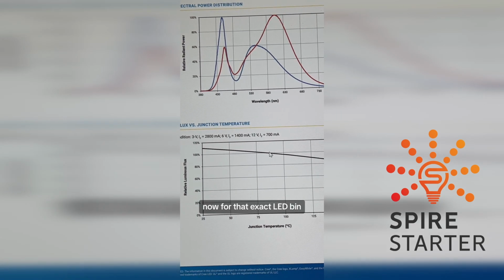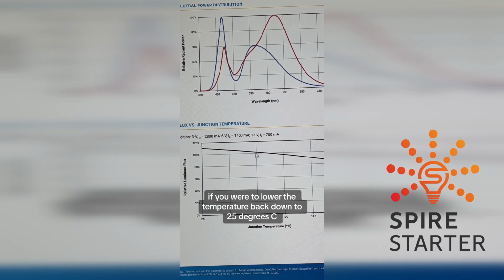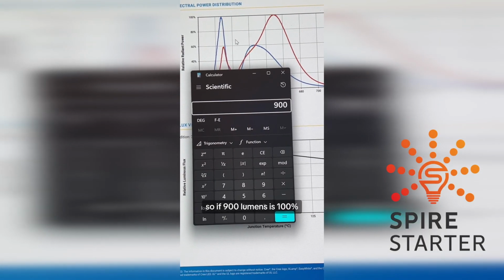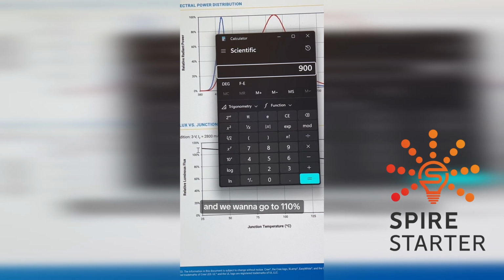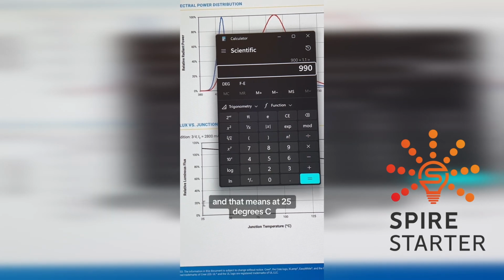Now for that exact LED bin, if you were to lower the temperature back down to 25 degrees C, then you're going to get a bump of 10% in that flux. So if 900 lumens is 100%, and we want to go to 110%, we multiply by 1.1, and that means at 25 degrees C, 110% of the lumens would be 990.